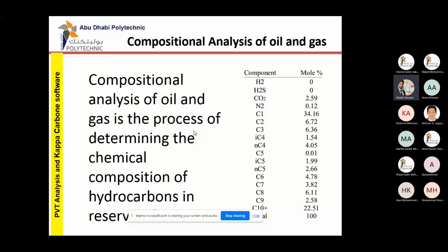When they run, the lighter component will reach the end first, then the second, then the third, then the fourth. And we put them on fire. From the flame and heat, we can figure out how much of each component is in the one drop of oil. That's how we can figure out all this composition.